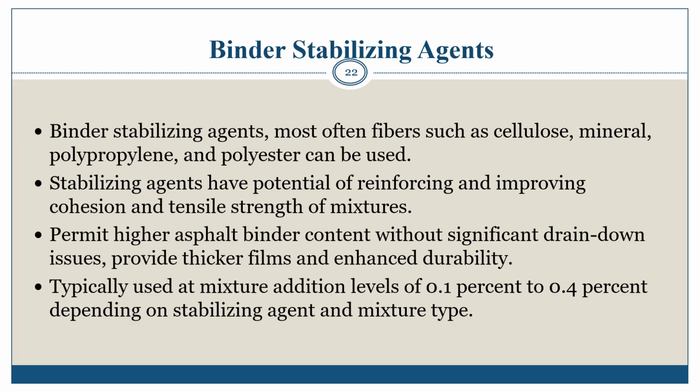Sometimes the additives are considered to be difficult to handle, but they do provide additional benefits to the mixture other than just drain down prevention. So it's very important to consider these added benefits before foregoing the use of binder stabilizing agents.